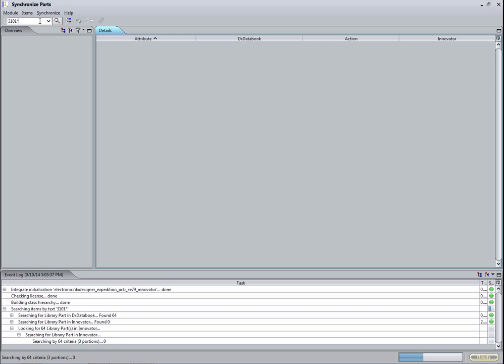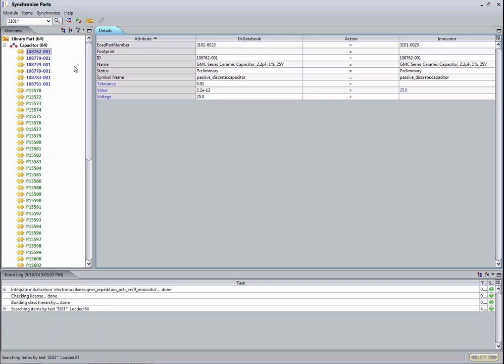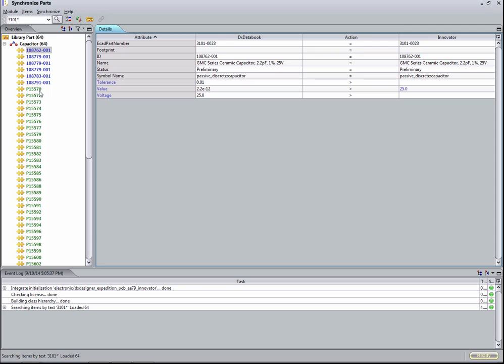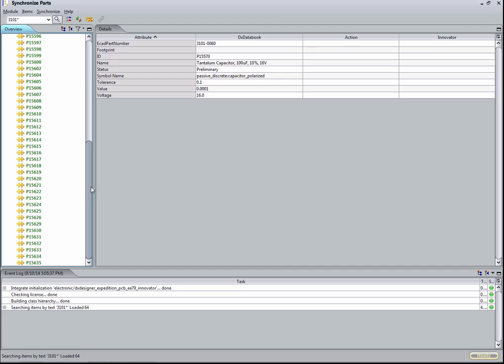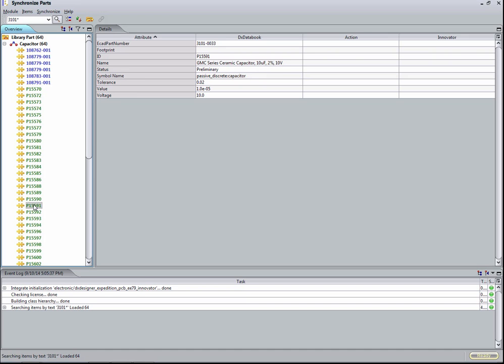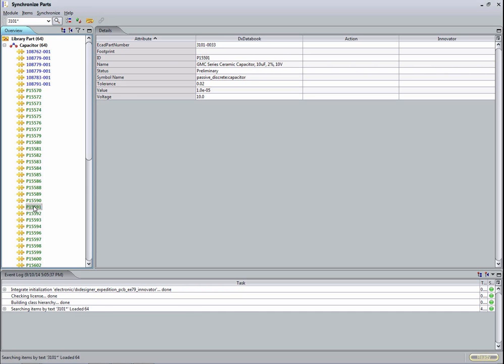The components shown here are marked with different colors. The blue color indicates that the parameter information in the development library is different to the one in the PLM system. Green marked components are not existing in the PLM system yet. Therefore, the column of the PLM system is empty. Black marked components are already synchronized. In difference to that, red marked components are not existing at all in the development library yet.